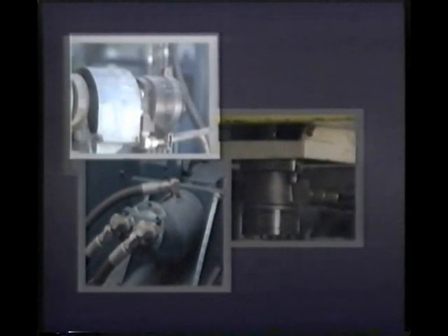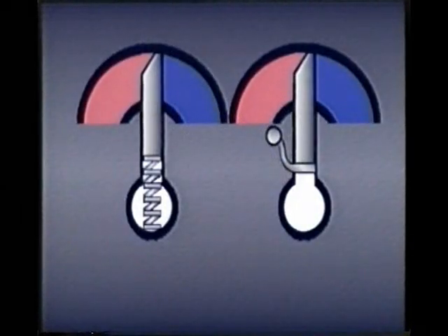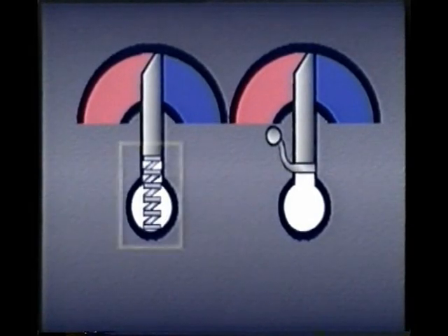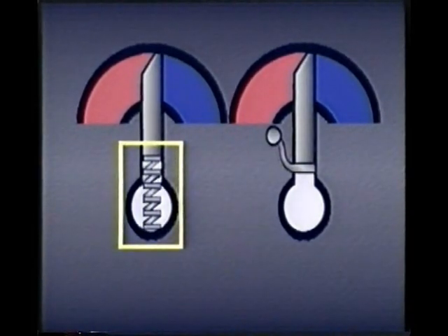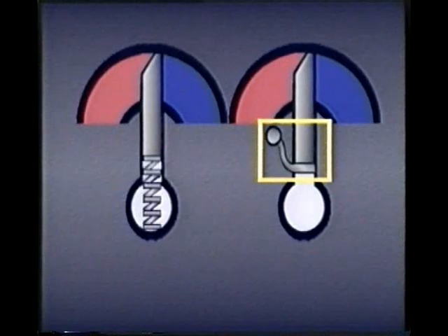In a vane motor, the motor won't turn until there is a seal between the vane and the cam ring. That means that centrifugal force cannot be used to force the vanes out to the cam ring at startup. In some vane motors, springs are used to hold the vane against the cam ring. This can be done with a coil spring or with a spring attached to a post.